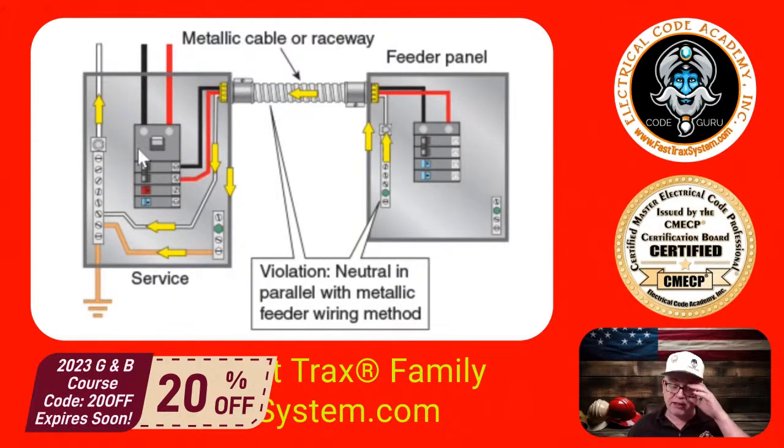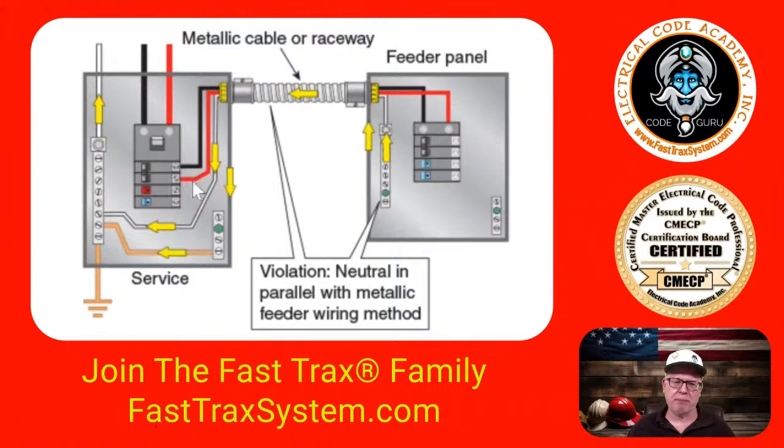All right, so let's look at this right here. So this is the illustration that we posed. So here's your main breaker, here's your feeder breaker, and this is a feeder, and it's coming down in this remote distribution panel, this feeder load center, however your flavor. And the one thing you'll notice is that it only ran 3 conductors. And so here, the neutral has a green screw and it's bonding it to the enclosure. This is what we're talking about, an improper case to neutral connection downstream of the service equipment.